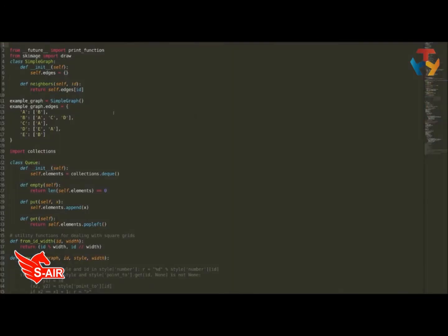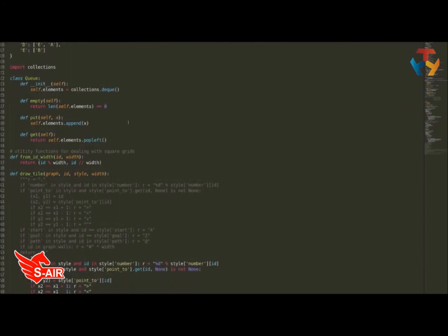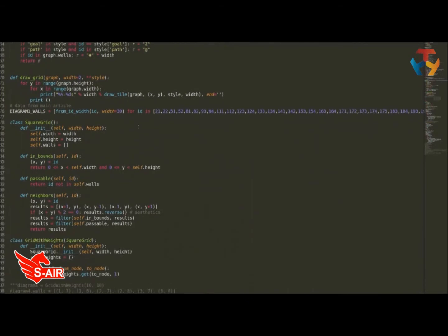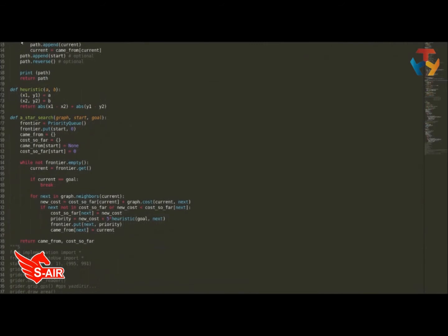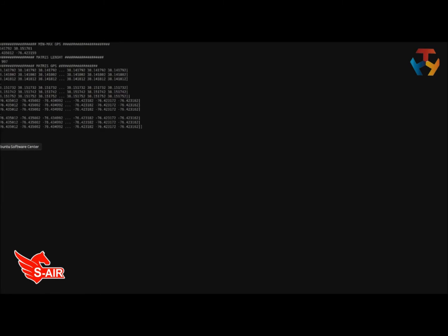The area between the given GPS coordinates for an obstacle avoidance mission is represented with a grid-based map or Universal Transverse Mercator coordinate system. On the created grid-based map, Dijkstra, A-star, Greedy and RRT pathfinding algorithms were tried. Pathfinding algorithms were tested on more than 100 scenarios. According to the test results, the fastest and the most efficient algorithm was found to be A-star. In the next step, the optimization of the A-star algorithm was done. For the development environment, the Python script language is used in a Linux operating system.